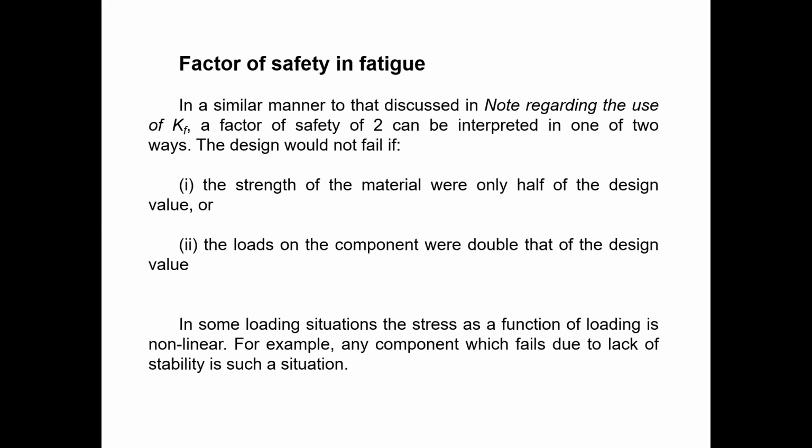So when we consider the load and stress, there can be a linear relationship. Sometimes it is non-linear. If it is non-linear, you can't use stress instead of load. So you should use the load values to compare something. Okay, so if you find different load values in different areas or different stress trace areas, you need to get the load value instead of the stresses, because stress does not represent the actual picture on that particular element. So you need to consider the load value, force value, because the stress-force relationship is non-linear.